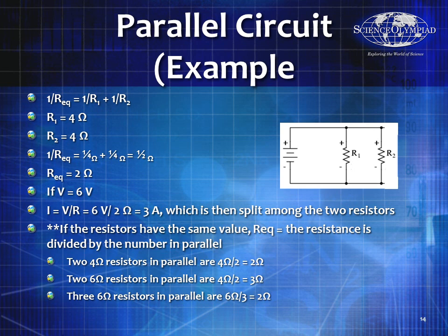This is really important because unlike series, it's sometimes difficult to calculate parallel, especially when you get multiple parallel. But to take this to the extreme, if I have 1,000 1 kilo ohm resistors in parallel, that will give me the same resistance as a single 1 ohm resistor, because it would be 1 kilo ohm divided by 1,000. And you can imagine trying to do that on paper would be virtually impossible, but through this shortcut I can easily calculate that value.